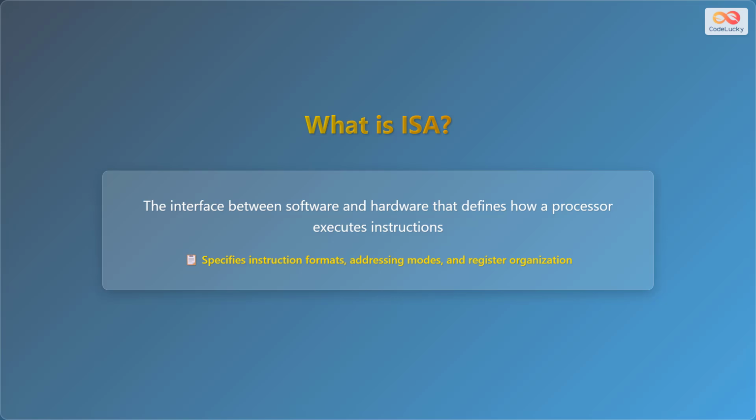So, what exactly is an instruction set architecture? It's the interface, the bridge between software and hardware. It defines how a processor understands and executes instructions. Think of it as the language that software uses to communicate with the processor. It specifies the instruction formats, the addressing modes, and the register organization that a particular processor uses. Instruction formats define the structure of an instruction, and addressing modes specify how operands are accessed.